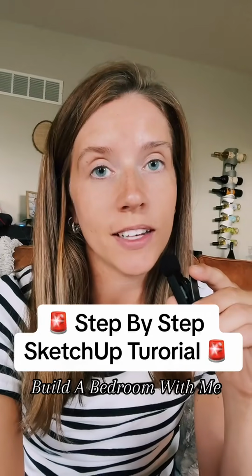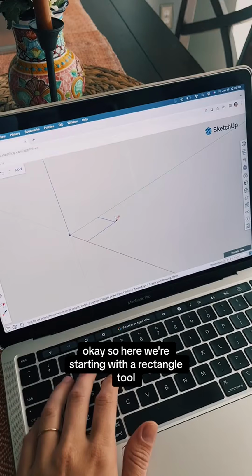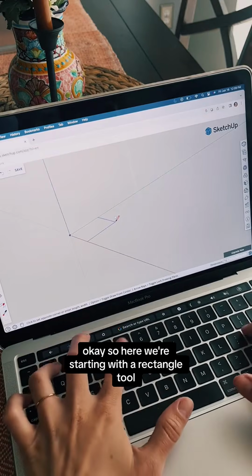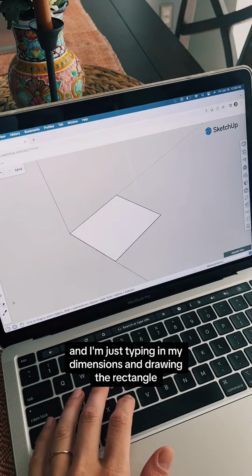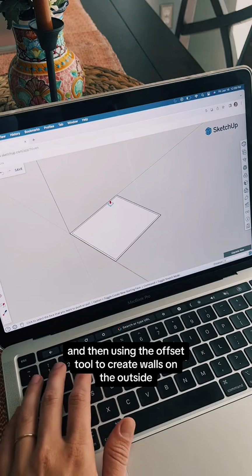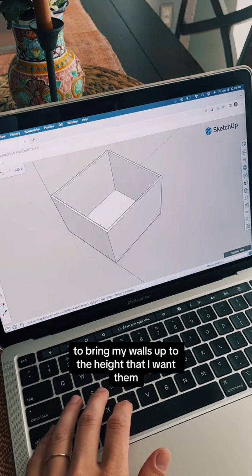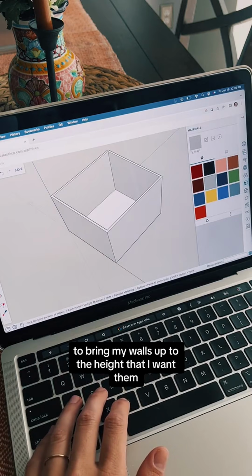I'm going to show you exactly how I model a 3D room in SketchUp Free in 2 minutes. Okay, so here we're starting with the rectangle tool, and I'm just typing in my dimensions and drawing the rectangle the dimensions that I want it. And then using the offset tool to create walls on the outside, and I'm using the push-pull tool to bring my walls up to the height that I want them.